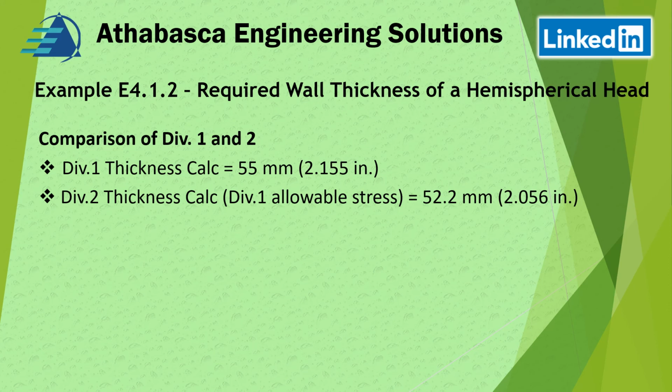The advantage of Division 2 is the allowable stresses. And then if you're going to follow Division 2, you're still going to have to deal with things like we mentioned earlier, these tolerances. So that's probably why I've never seen Division 2 rules used, but ASME allows that. But you need to also check with your local authority to confirm whether they'll actually allow that as well. So, yeah, check with them.